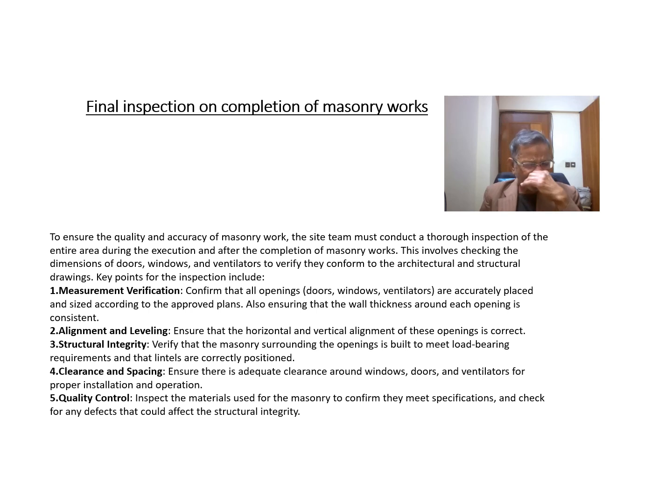Alignment, leveling and plumb of the masonry are to be checked once again, as we checked them during the execution. Structural integrity is to be verified. It is very important that the structure should be strong and sound and as per the drawings and the specifications. Clear spacing, as I discussed earlier also, there should be clear spacing at all the sides of the openings, like doors, windows, ventilators, arches, and everywhere.